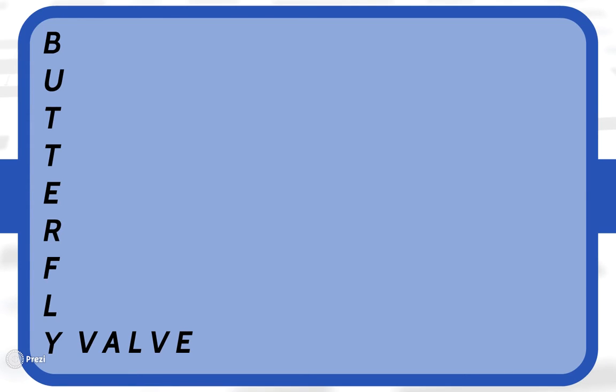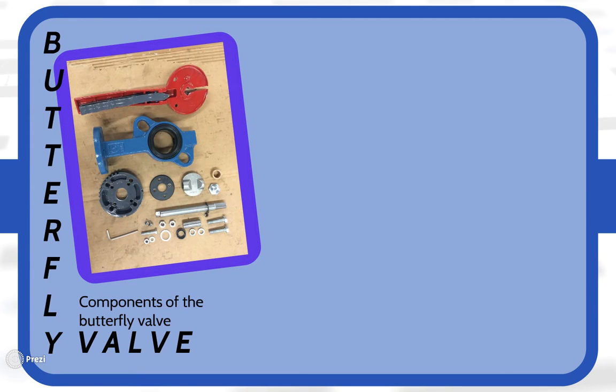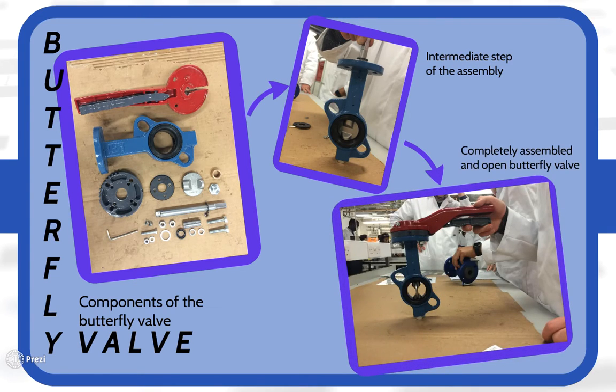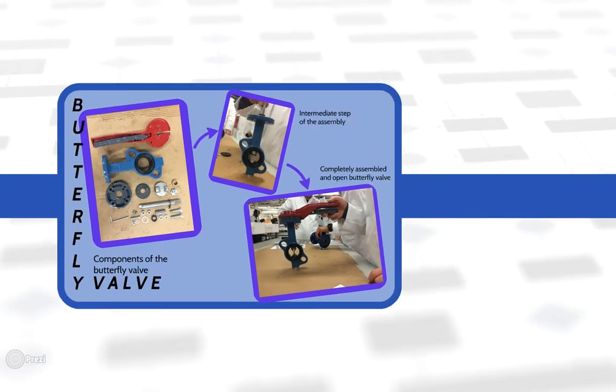The butterfly valve. The butterfly valve is a compact and light valve. It has a quick on and off system with quarter rotational turn. This valve has a low pressure drop and a high pressure recovery. It is used mainly in slurry services, cooling water, and fire protection.